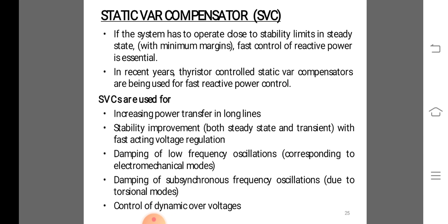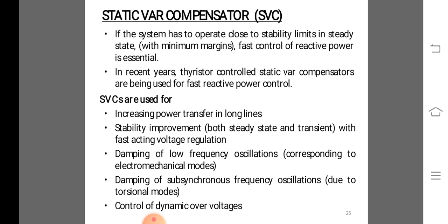The capacitor bank often includes in part harmonic filters, which prevent the harmonic current from flowing in the transformer and the high voltage system. Filters for the fifth and seventh harmonic are generally provided.